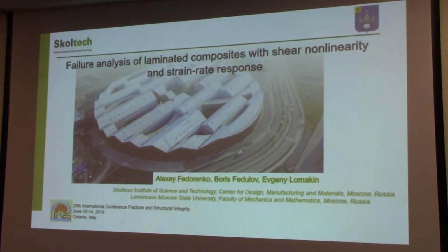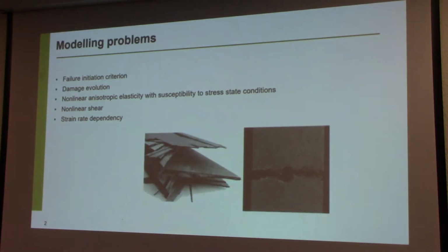About a modeling approach for failure analysis of composite materials. And some elements of this approach were applied in some industrial application for composite structures. The problems that will be considered are failure initiation criterion, damage evolution, nonlinear anisotropic elasticity, nonlinear shear, and strain rate dependency.